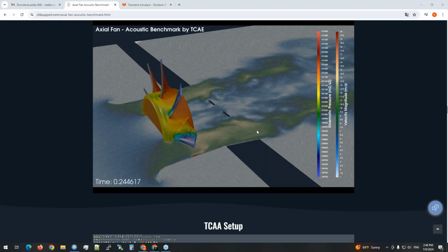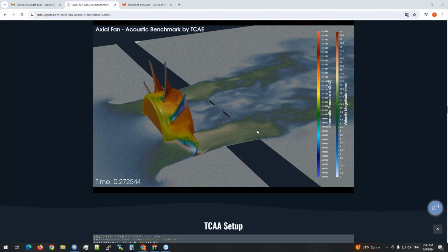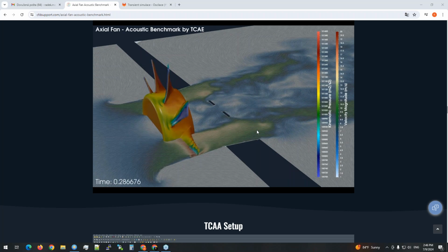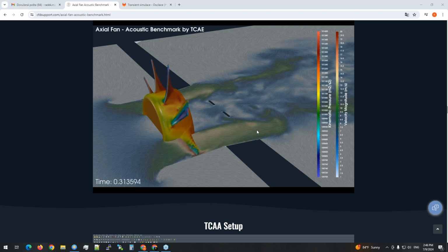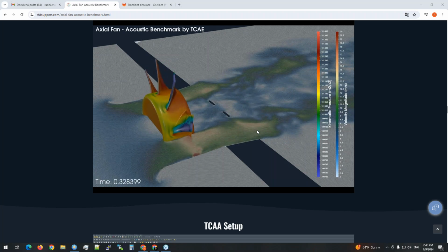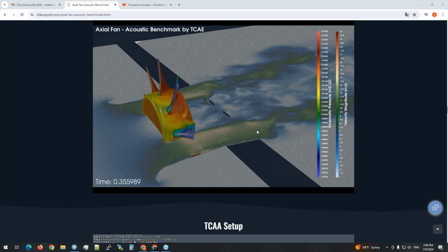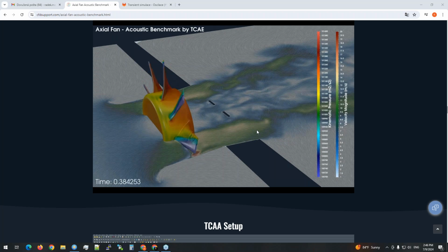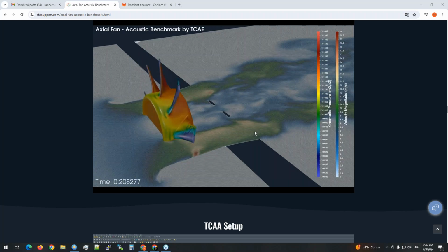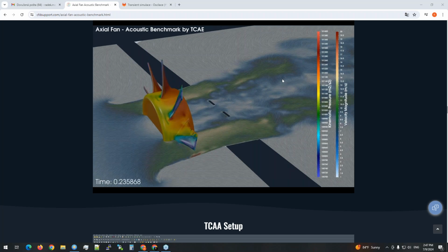If not directly in the graphical interface, we can use scripts that change the boundary conditions at the inlet, for example, to something we call time varying boundary conditions for whatever quantities we select. I'm talking here about transient simulations, but we can still change what's at the inlet or at the outlet during the simulation time. So there are a lot of possibilities regarding this.